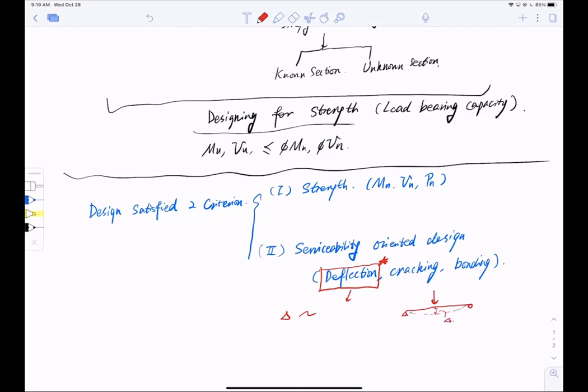The modulus of elasticity. Exactly, that's E, right? And then I had to know the section, right? So cut the cross section, for example, this is square. What do I need to know about this section? The moment of inertia. Exactly, moment of inertia. Thank you, that's critical, right? So essentially all we need is Young's modulus and moment of inertia.